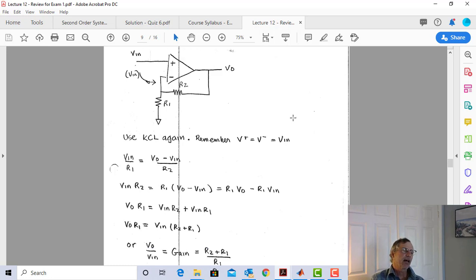Okay, so those are the basics of op-amps, and you can see that for an ideal op-amp, the analysis is really easy, and the circuits will typically fall into inverting, non-inverting, or voltage buffer. Of course, op-amps are used in all kinds of configurations, but this is mostly what you see in industry. If you see one that's not in this configuration, just write a couple of equations and you can figure it out.